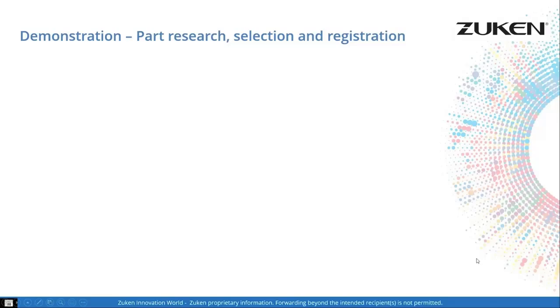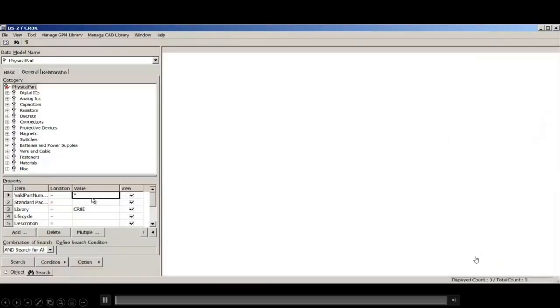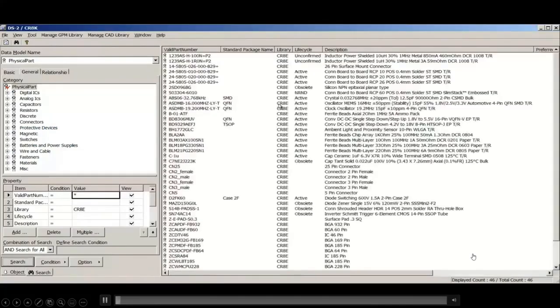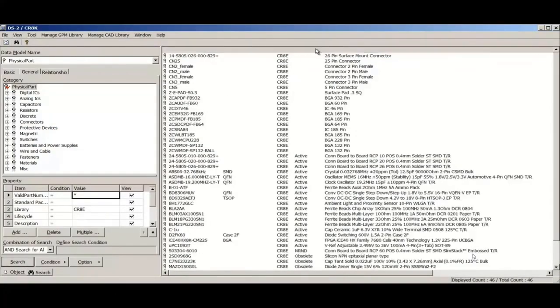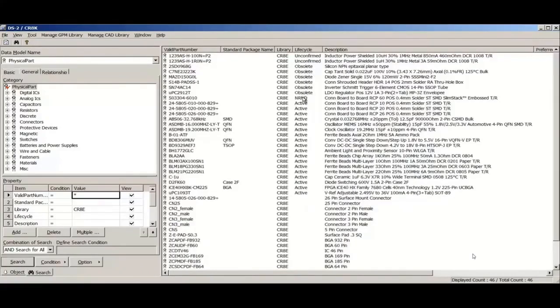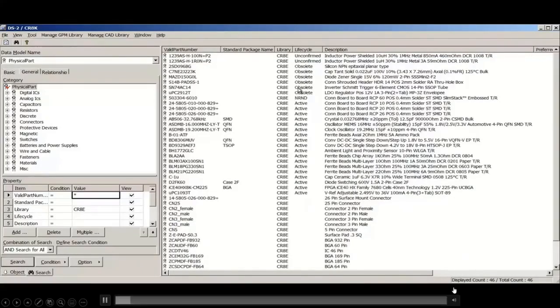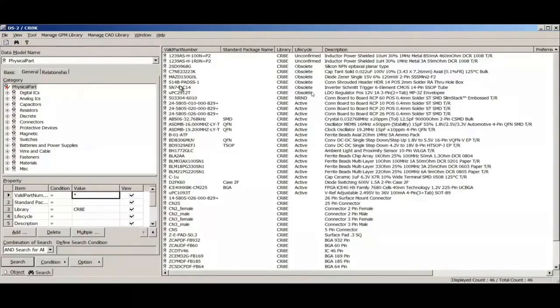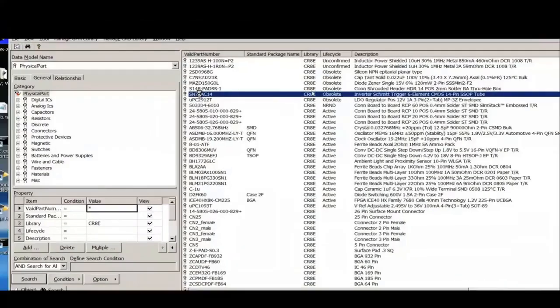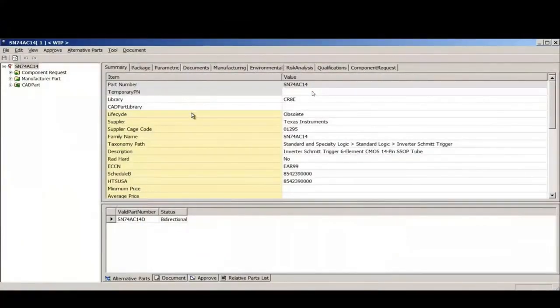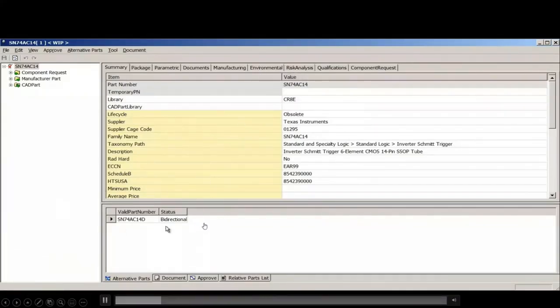Now, just looking at how we handle obsolescence of a particular part. Within the CDB, within the DS-CR, we can find the components and flag from SiliconExpert which ones have been marked up as obsolete. And that can be automatically passed from SiliconExpert, as I said, on a daily basis or on a 4-hour basis. You can extract the information from SiliconExpert. We can see that it's obsolete. We can see the part numbers.